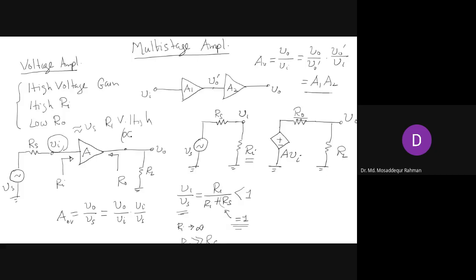So we said for an ideal amplifier, the input resistance should be infinite, and that's why we say the ideal op-amp has infinite input resistance. That is the feature of an ideal amplifier. The common emitter amplifier has a low input resistance Ri, and that affects the overall output voltage because it will cause a large loss of signal in the source resistance, and Vi will be substantially smaller than Vs. So you lose some signal at the input side. That is the downside of the common emitter amplifier.